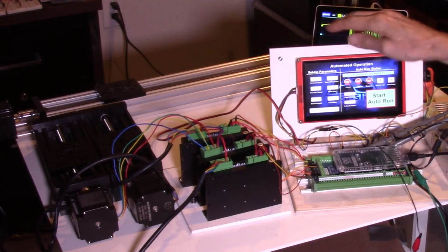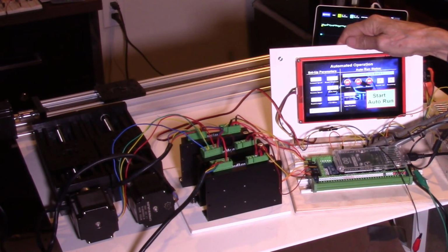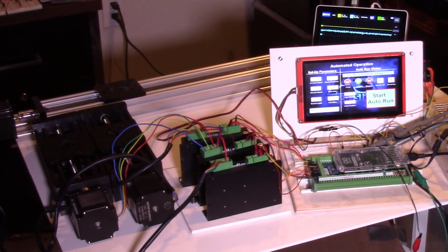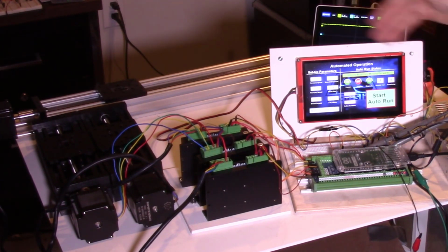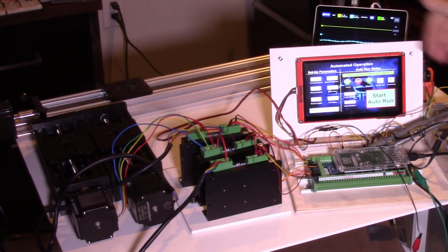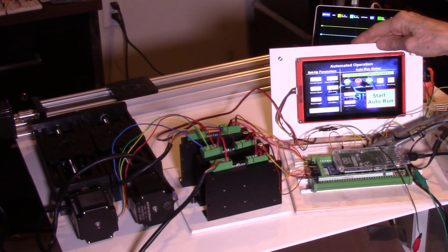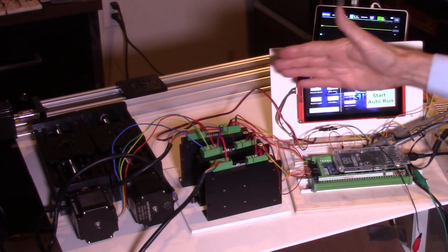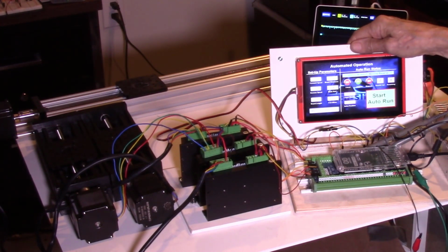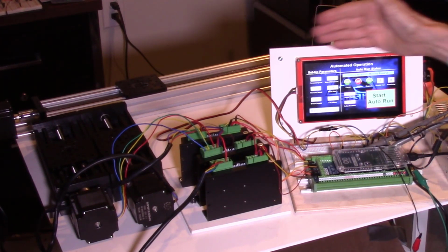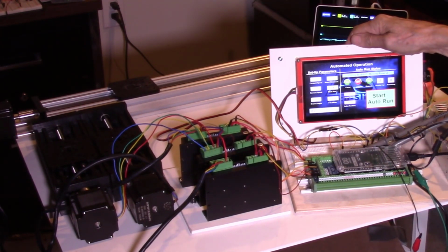So again, doing the second board, move the indexers in. Of course, my magnets are going off and on over here at the same time. The indexer's moving forward because the magnet's activated. When I finish the cut, it moves the indexer back to move the board away from the bandsaw blade, and then moves the indexer back. So it's all automated. Did that twice for 2 boards.